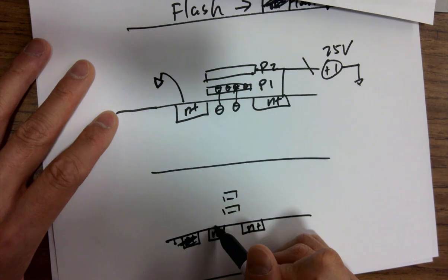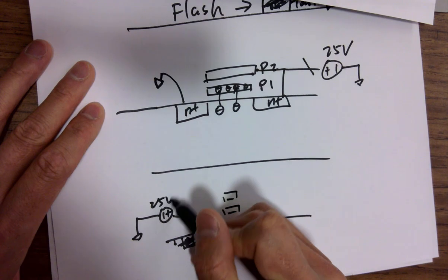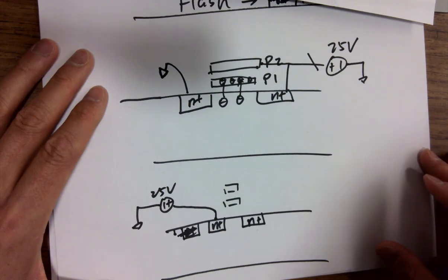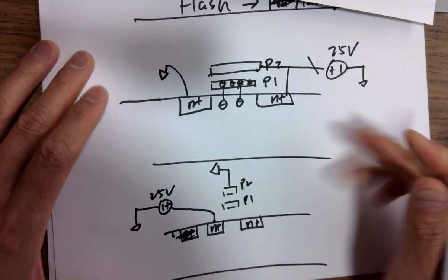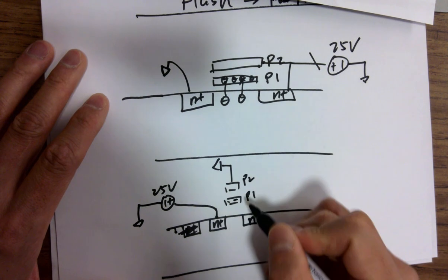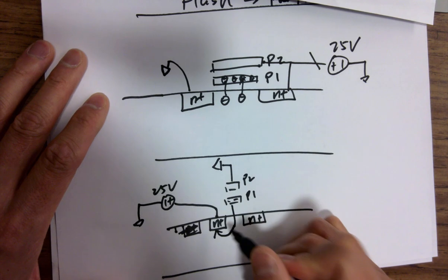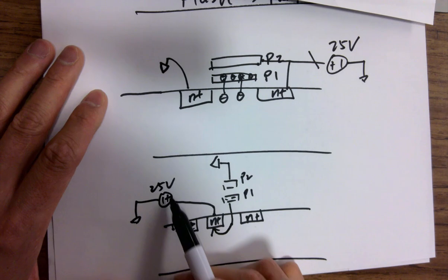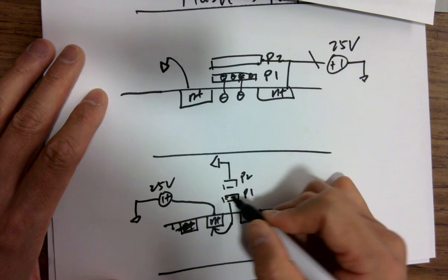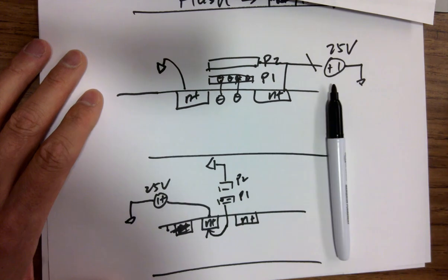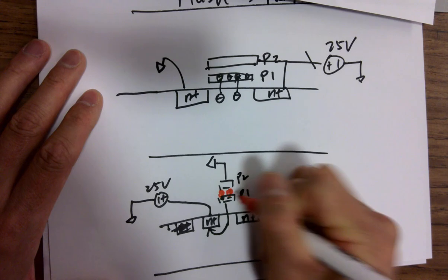So what you do is you put a high voltage here and you ground the gate P2, and the electrons pre-charged in P1 will get out from this one and be attracted to the anode of the power supply, because high voltage is able to do it, right? And then it will even go further and turn the floating gate positively charged, right, to plus.